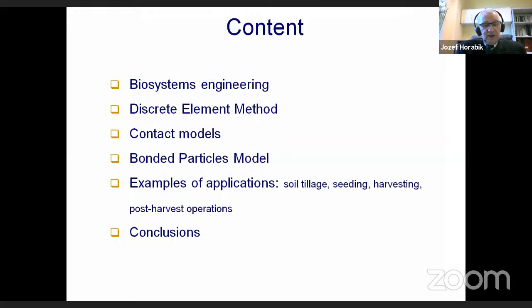Agriculture granular materials present a very wide range of shapes, from nearly spherical to ellipsoidal or to concave particles of fluids and tubes. And the complex shape of particles are often modeled for DEM application by clusters of rigidly joined spheres. This method is known as the multisphere method.